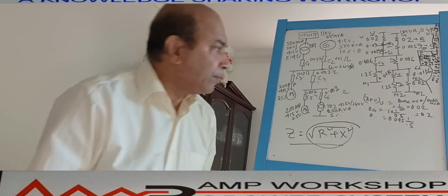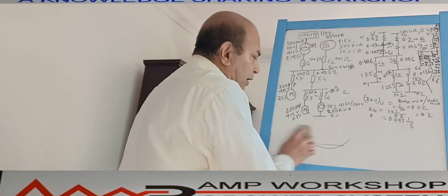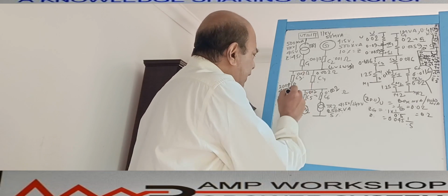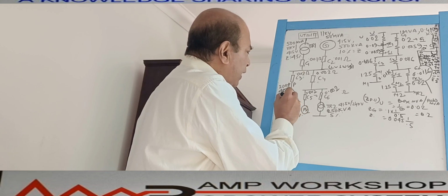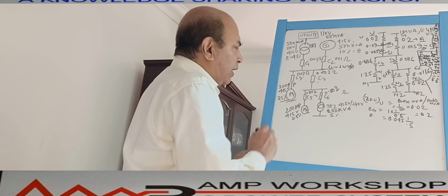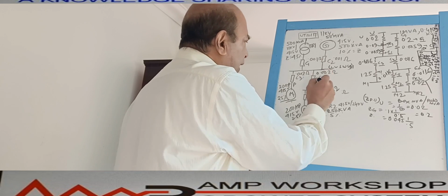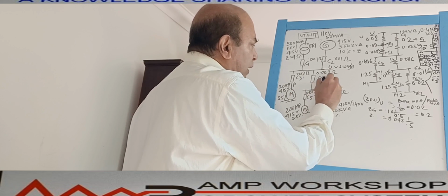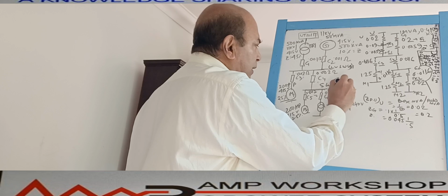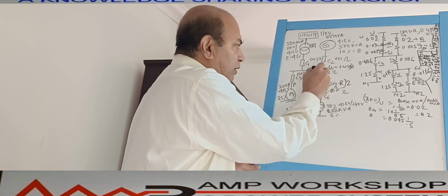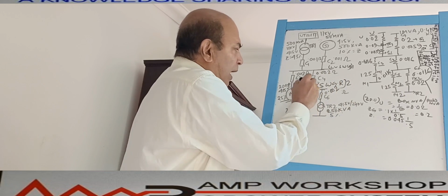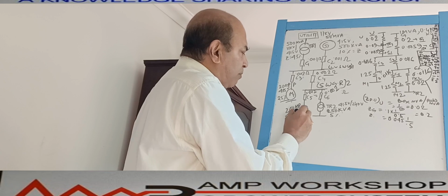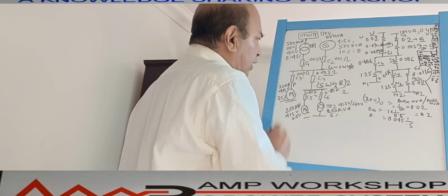So that is the cable ohmic value. Now the next part is this cable is connected to a motor. That motor is 25% impedance, 200 HP, we have already said. And the second cable is connected to another switch gear, which is located slightly away. That is also in the low voltage switch gear, but suppose it is switch gear 2, located slightly away from this, and that is connected by this cable. Then from the switch gear there is also another same size of motor, and there is a transformer.